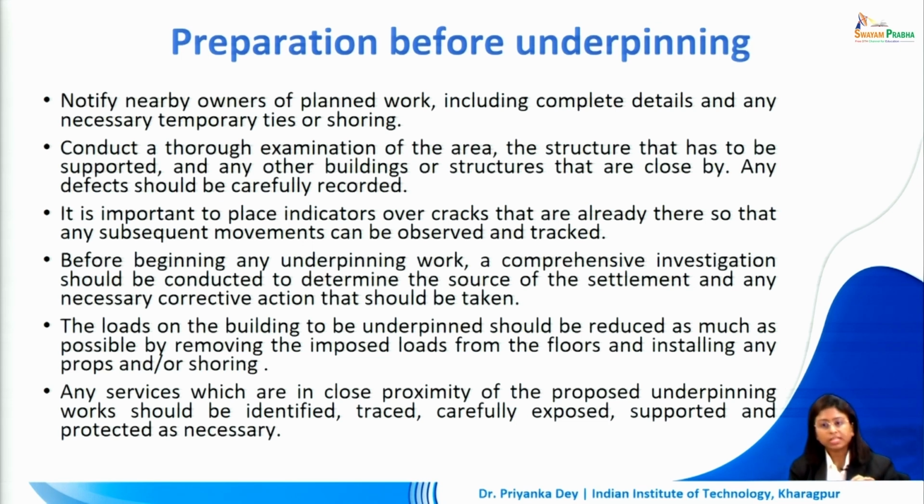the construction transformation. Now, before beginning any underpinning work, a comprehensive investigation should be conducted to determine the source of the settlement, if any settlement is happening in the ground, and what corrective action has to be taken, anything that needs to be taken before we take up this process.